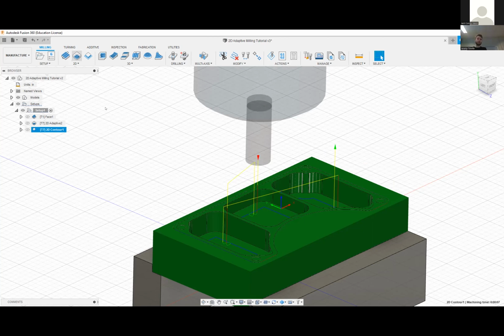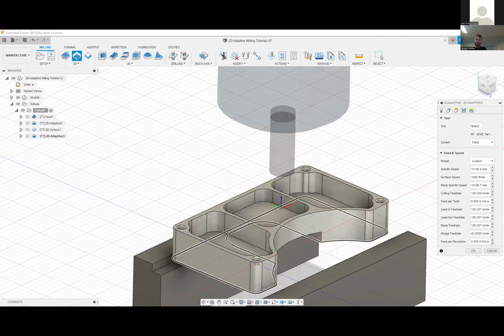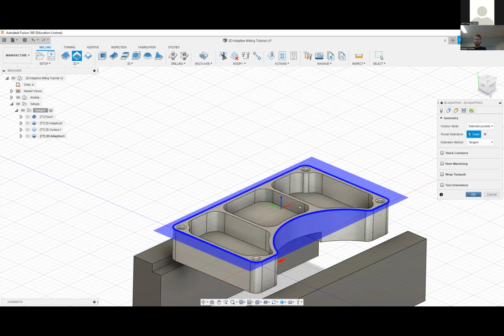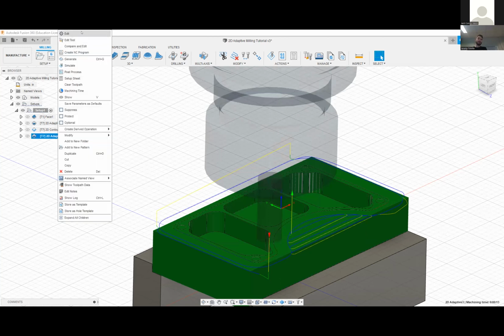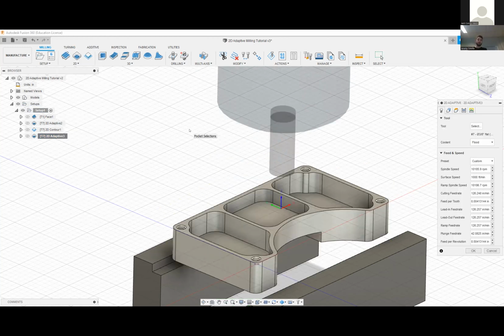So I talked about my problem with it not getting that bottom edge correct, right? See that dip in the middle isn't doing what I want it to do. So that outside actually has the same contour as the top edge. So I'm going to select this top edge. But if I hit OK, it'll just try to cut at that level. It's not cutting lower. So I'm going to force it to go down to the bottom level and use that edge. This is why we kind of have to play to get it to do what we want sometimes.